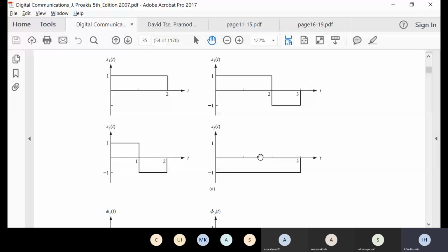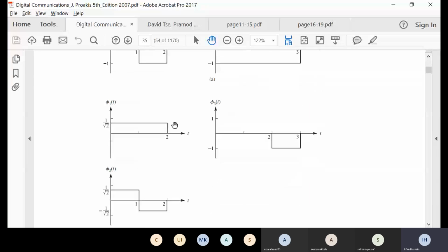Okay. So we won't go into lengthy detail, but just to tell you that you might have, let us say, so this is S4 actually. So you might have many signals, S4 signals, but your orthonormal basis just comes out to be 3. So all of the above signals can be represented in terms of these 3 signals. Okay, so this is the dimensionality of your signals, right?